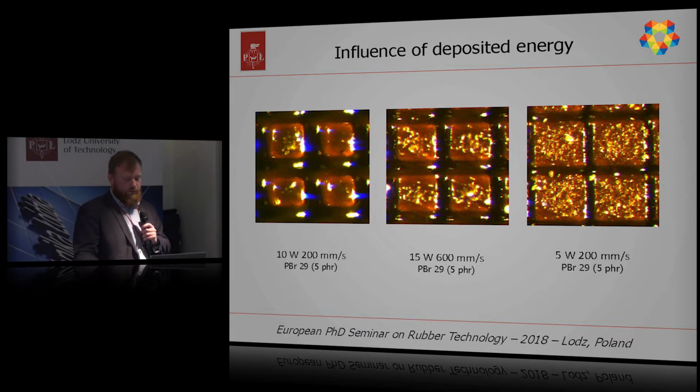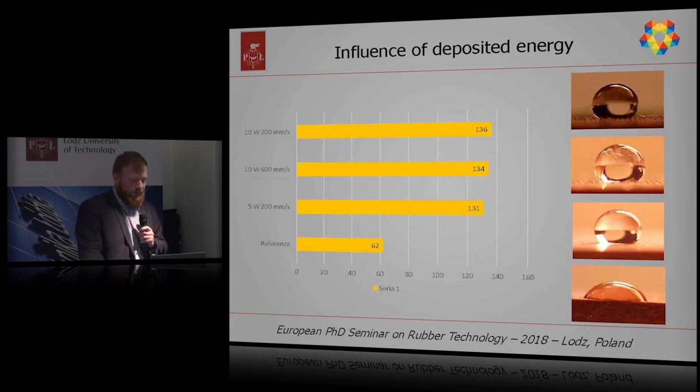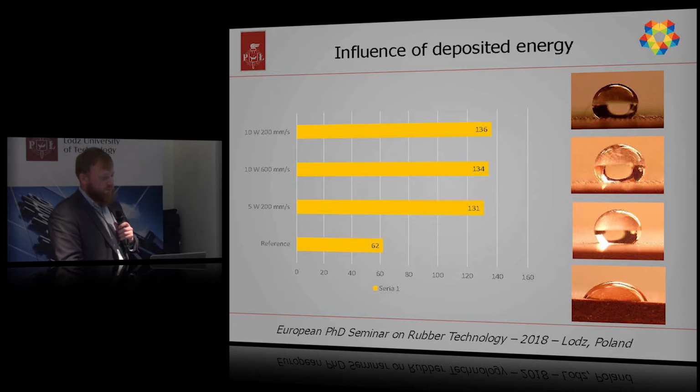So when we have pictures, maybe we can check wettability. And wettability we can say increases when patterning is made on the surface. Compared to the reference non-patterned sample, the contact angle increases from 62 degrees to 136 degrees.